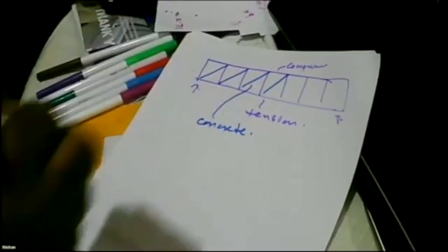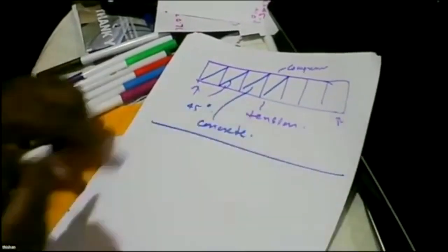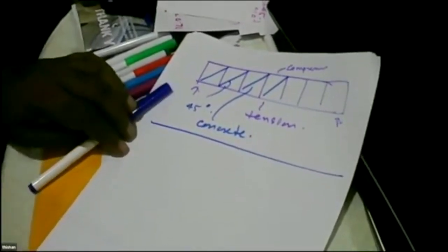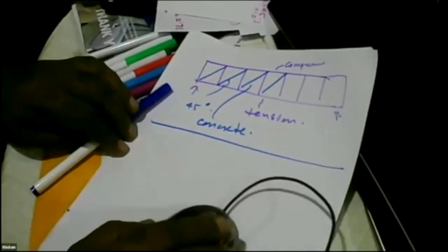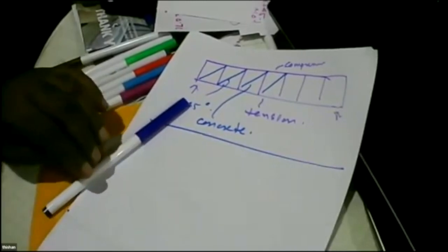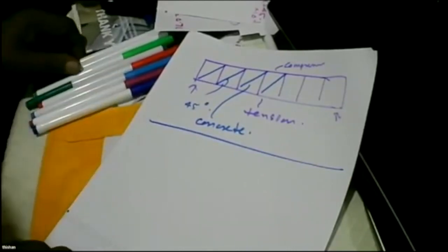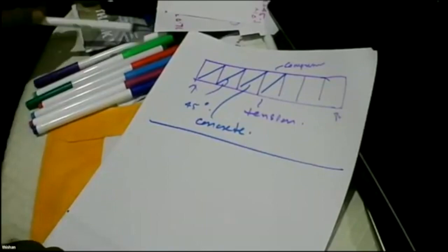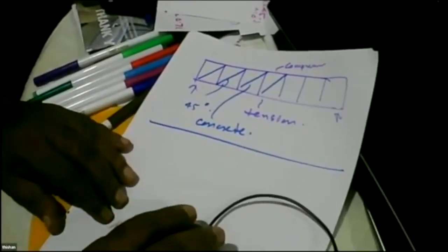And in BS 8110, this angle is 45 degrees. And that's the place where the Eurocode differs. Okay? So this is what the BS is. Now let's look at what the Eurocode says. The equation for the Eurocode is given in the document, I'm going to share.